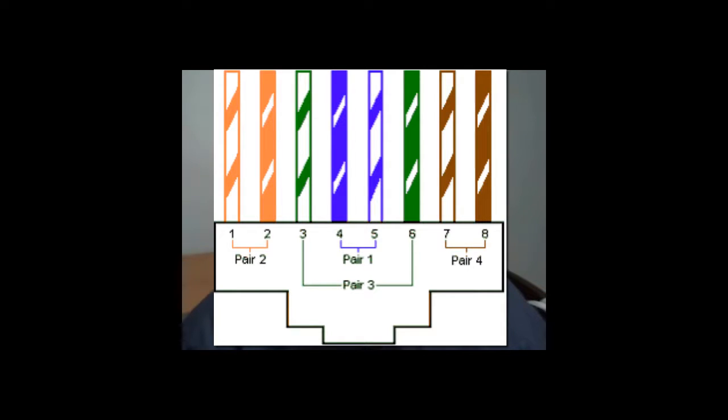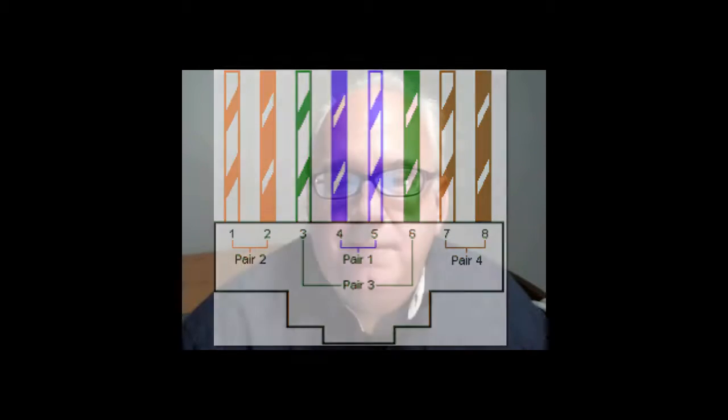So you'll notice a few things that can help you remember this order when you're going to want to do that. First, the wires alternate between a striped wire and a solid. Second, the 2 pairs on either end are with their mates. So we have white-orange and orange, and white-brown and brown. Third, the middle pair starts with the white-green that we will be using, but then it jumps to the solid blue. The next one must be striped because of our rule, so the remaining striped wire is the white-blue wire. And the only other wire that's left is the solid green at that point.